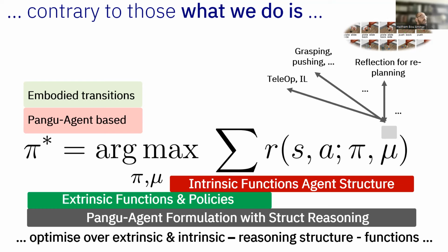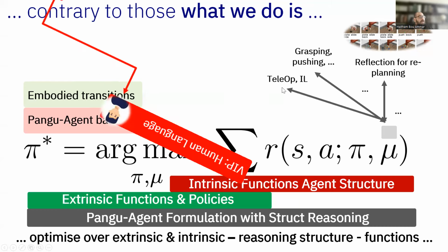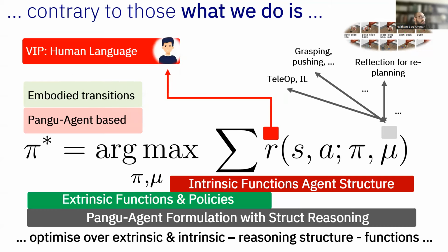So instead of having the non-expert write a reward function for us, we allow feedback to come from standard human language. This human language feedback gets rid of writing a reward function, and allows non-expert users to tell the robot, bad robot, you did bad, or good robot, you did good, and maybe even give a more detailed plan, saying, okay, look, you did the first two steps right, but you tried to open your gripper in the wrong place. You should have closed it first, then opened it, and so on. Based on that, this goes back to our LLM. The LLM can fine-tune or reflect in order to give us a better plan.